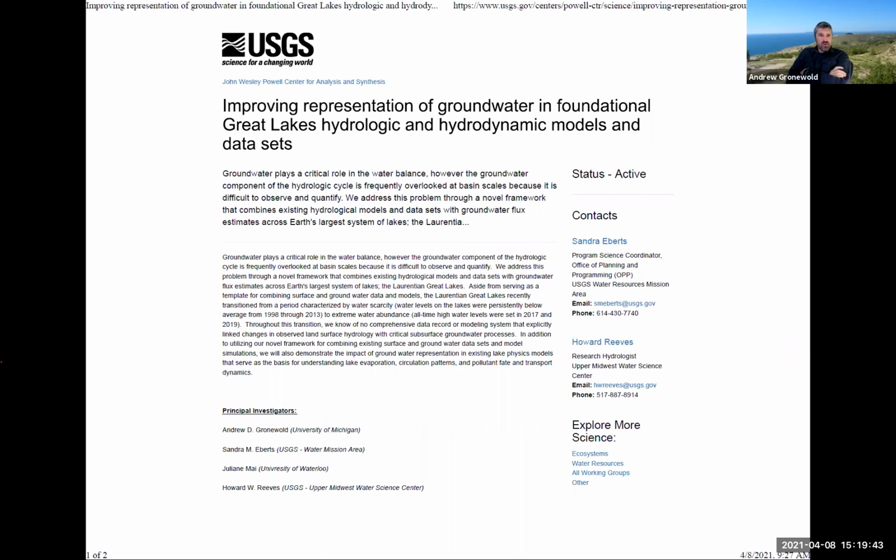Initially, we were going to try to develop a coupling between WRF-Hydro, the Weather Research and Forecasting model hydrological subroutine, which had been developed by NOAA and by the National Center for Atmospheric Research, NCAR, for the entire country and also for the Great Lakes Basin. And we were going to try to couple that with a conventional subsurface model like MODFLOW and/or GSFLOW. What we've done instead is we have recognized the complications there, and my postdoctoral fellow Yuen Mei is almost working exclusively right now on trying to customize MODFLOW and GSFLOW to the entire Great Lakes Basin using some stratigraphy data provided by Ed Siddiqui in Canada, using some output from their model they recently ran. So the short answer is right now we're focusing on MODFLOW and GSFLOW and customizing it to the entire Great Lakes Basin, although we're open to other models as well.